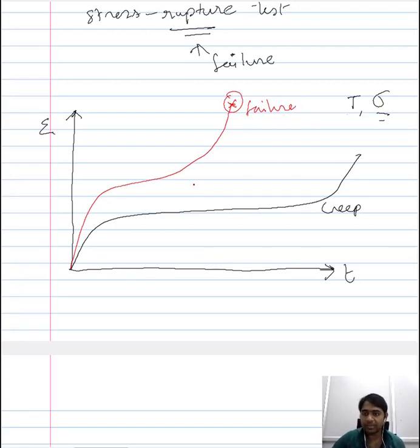So when you compare, for a given material, schematically, the creep curve and the stress rupture curve, of course you would observe the different stages. You would observe the tertiary stage, you would observe stage 1, or the combination of instantaneous and transient creep stage. The only stage that shows a significant difference is the steady state creep stage, wherein the rate is noticeably increased when you increase the stress involved in the stress rupture test. So this is the schematic difference that you would observe in the behavior of the material when you compare the stress rupture test to that of the creep test.